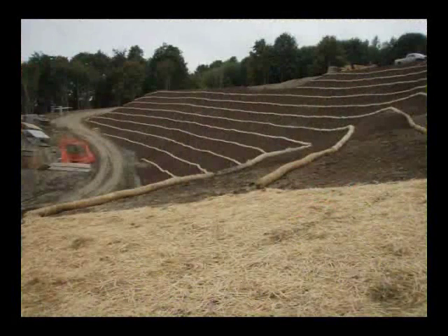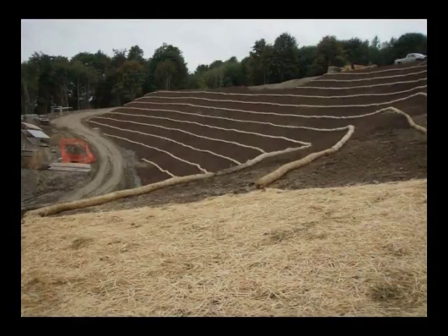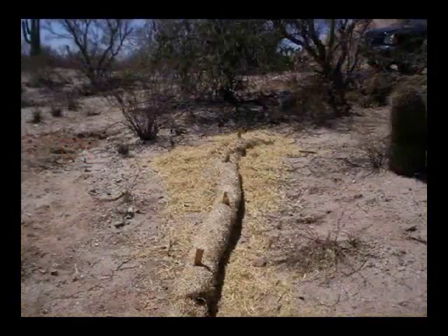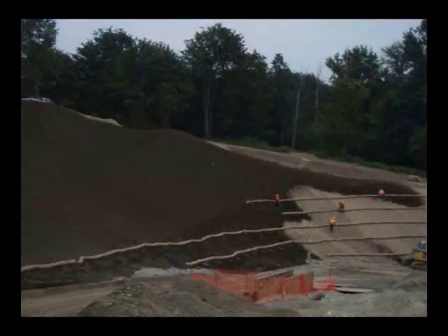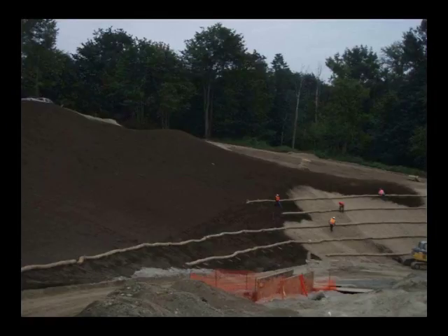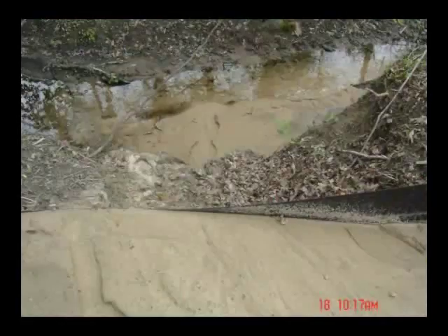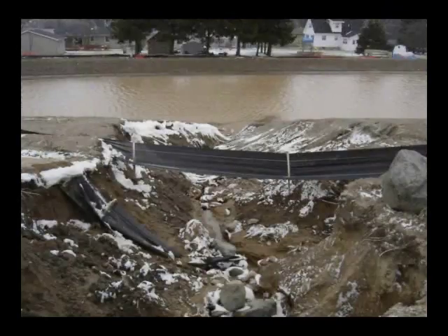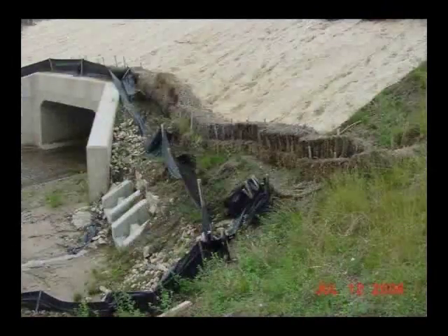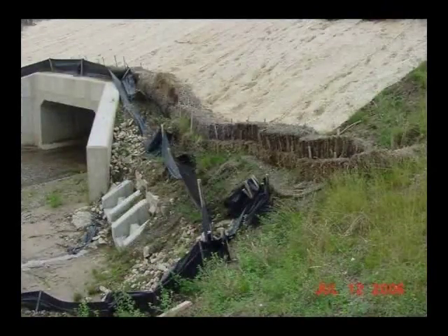When used as silt barriers, straw wattles and compost filter socks should be applied in much the same way as silt fence. Wattles must be staked, but compost filter socks may be heavy enough to stay in place without staking. Neither wattles nor compost filter socks have to be trenched in, but both must be installed along contour lines, and the ends must be secure so water and sediment cannot flow between pieces. When sediment accumulates to 40 to 50% the height of the barrier, the sediment must be removed. Barriers that have been damaged by excessive sediment loading, vehicle traffic, or general wear and tear must be repaired or replaced to restore full function.